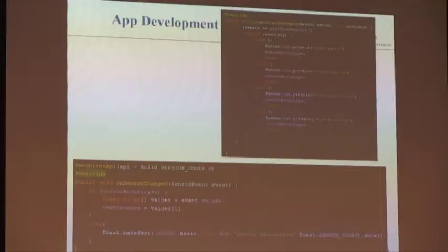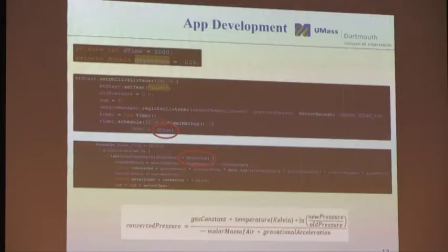And this is a snippet of our Android Studio code. This is specific to our pressure sensor. We were able to have an accuracy change function. This actually checks the accuracy of the sensor, and I've coded it so that it's only going to work when it's medium to high accuracy. On sensor change, it uses an if statement, and it only writes that new pressure value if it's high accuracy or medium accuracy. Otherwise, it will give us a little message saying that's inaccurate.